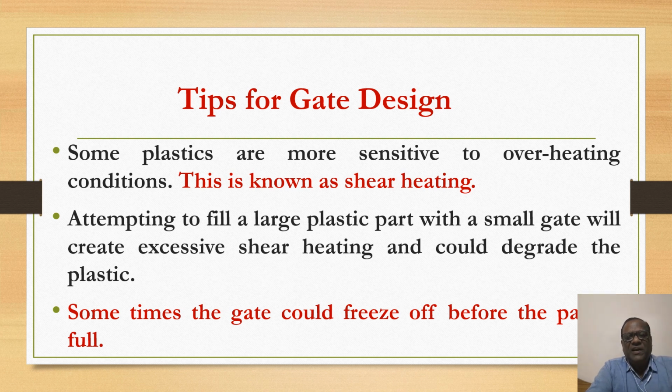Attempting to fill a large plastic part with a very small gate will sometimes create an excess amount of shear heating. If there is shear heating, that means the temperature will go up, and excess shear heating could lead to degradation of the plastic inside the mold, and sometimes the gate could freeze off before your cavity is entirely filled.